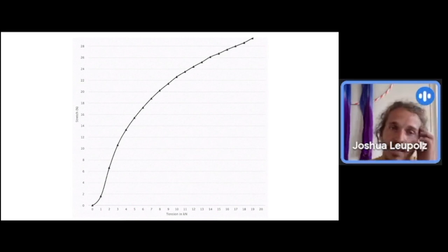When I repeated with the same webbing and did the test, stretching out quite fast, I was settling it up at 2.5 kilonewton, waited a bit until everything settled down, and then pulled relatively fast, in roughly 1 second, to 5 kilonewton, just having a pulley system and doing one hard pull on it. I measured the elongation and got an increase of only 2.2% of stretch. So it's roughly 1/3 of what we would expect from this curve.